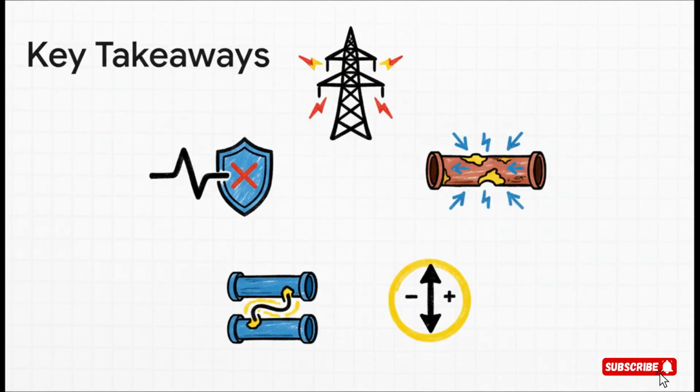So let's wrap this up. What are the big takeaways? Stray current is an external threat, totally different from galvanic corrosion. The real damage happens where DC current discharges from your structure. Finding it involves systematic field analysis, looking for those potential shifts. And the fix, for DC, is usually a properly installed bond. AC is a unique safety and corrosion hazard that needs its own special mitigation tools.